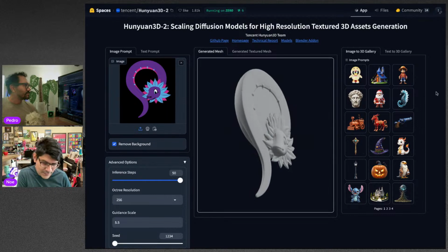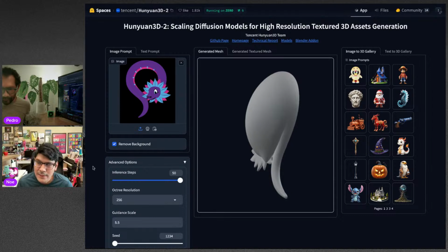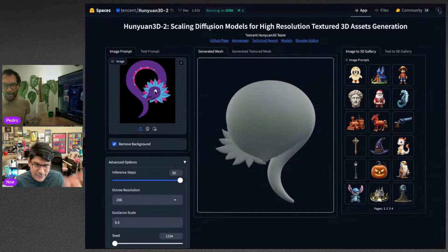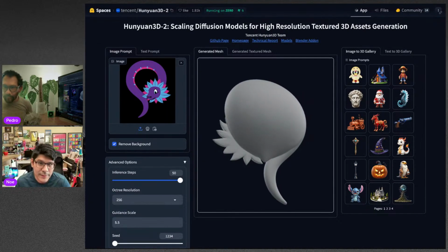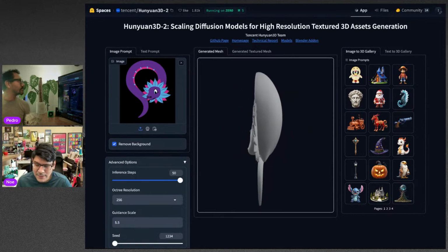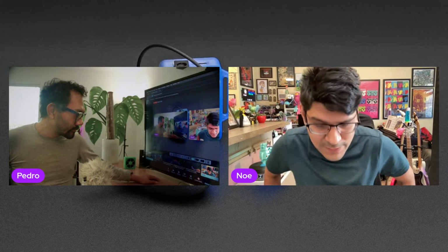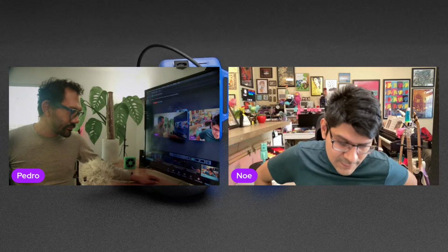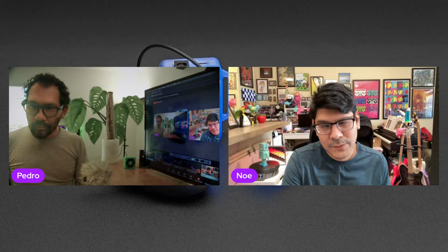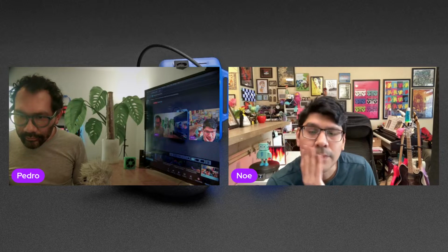It's more like solid modeling. They're not meshes, they're solid surfaces. It's code, and you can change the length and the width because it gives you auto-generated parameters, like wall thickness, width, length, height. I need to figure out what to make, maybe dividers for a tray. It has extrude and loft and all those standard modeling tools on top of a text to 3D prompt built into it.